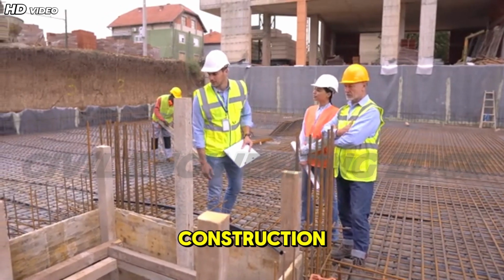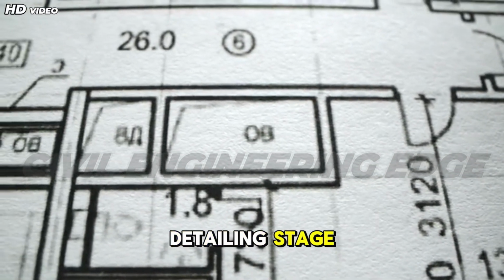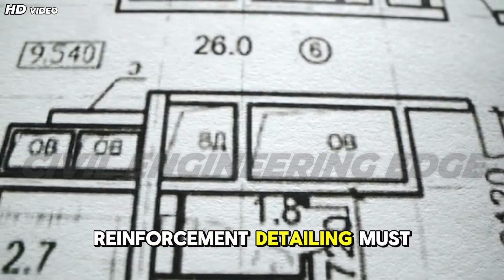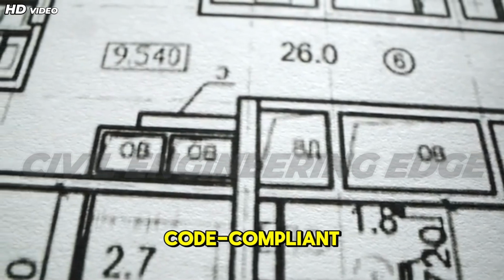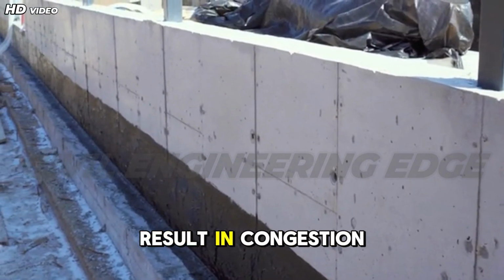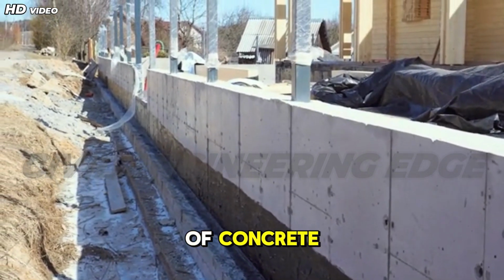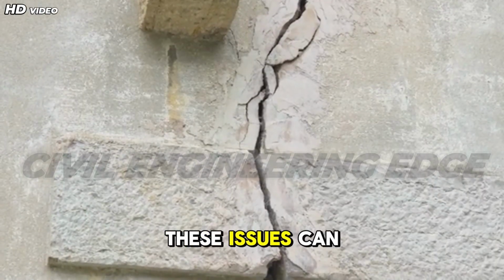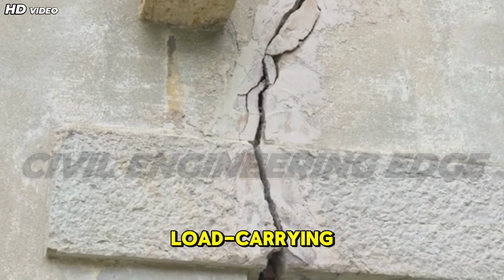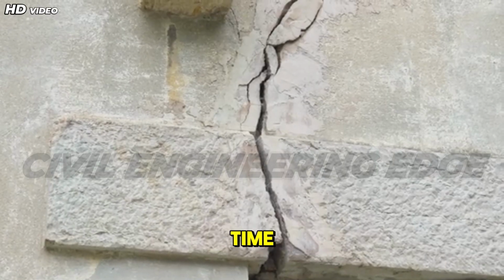and durable construction. Practical considerations begin at the detailing stage. Reinforcement detailing must be clear, code compliant, and easy to execute on site. Poor detailing can result in congestion, improper bar placement, and inadequate compaction of concrete. These issues can significantly reduce the load carrying capacity of columns and lead to durability problems over time.